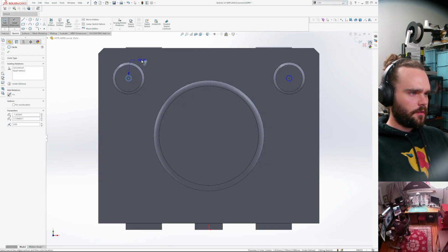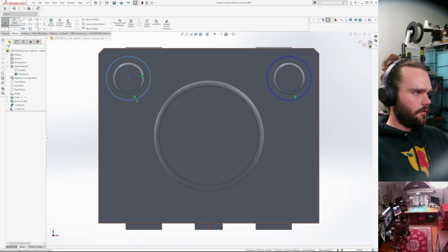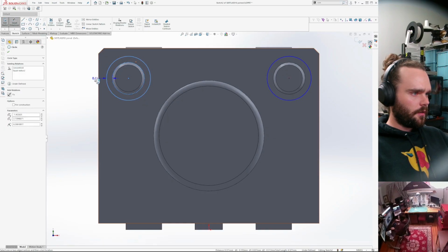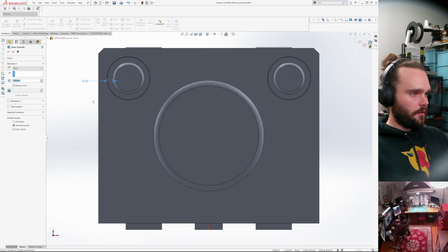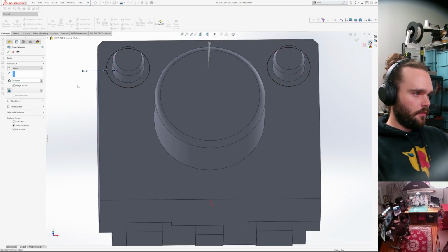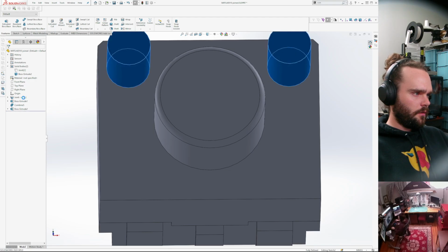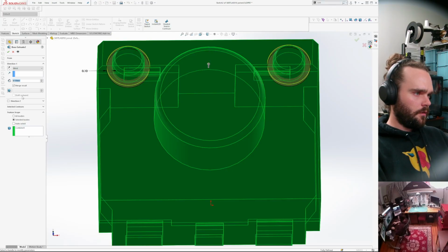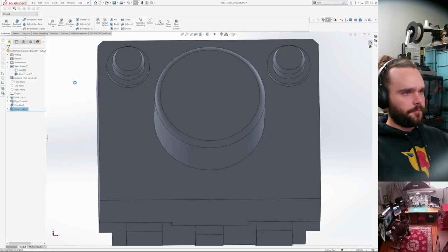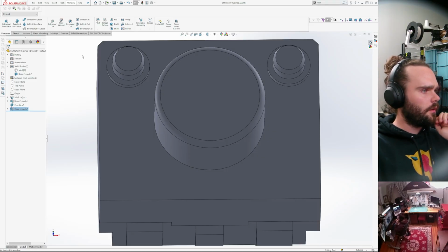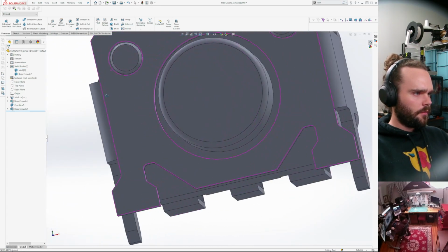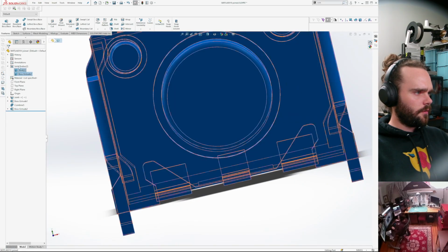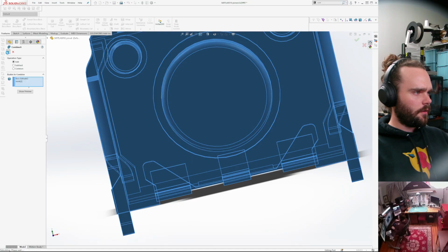I want this guy, and then we're gonna do, okay, so now these guys are touching now, so we're gonna do this, insert, features, combine.